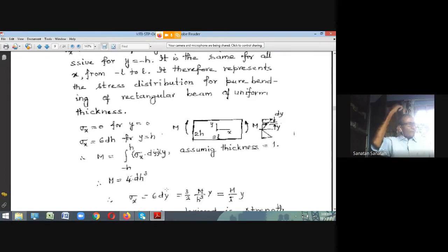At the same time, those constants are also going to be linked to the boundary loading, because the stresses are actually specified by boundary loading. The boundary loading is again a derivative of that function, and therefore they again have some linkage amongst them. So if you take a polynomial, it will satisfy the equilibrium equation, that is okay. But those arbitrary constants will be selected such that they also satisfy the equilibrium equation. When you plug them into the equilibrium equations, if they are 0, they will always satisfy. But if they have certain linkage between them, then it is going to be settled.